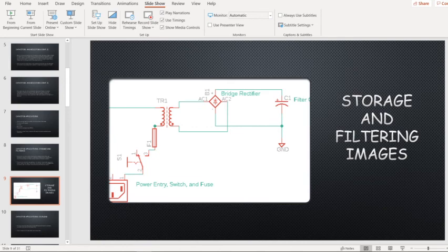The idea behind the safety capacitors is that they don't fail short. They fail open. If the component is intact and there's no cracks inside of it, then it's going to fail open, which is the ideal. But in the case of these RIFA capacitors, that's not what's going to happen, not because of the dielectric inside, but because of the shell that's supposed to seal it.